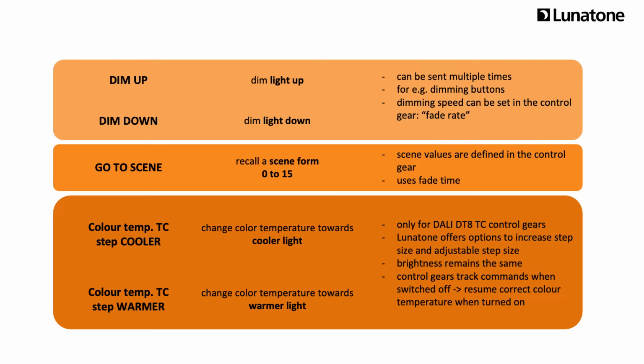Please also note that the commands step warmer and cooler only change the color temperature. The brightness stays the same. Furthermore, control gears react to these commands when they are turned off as well, so when they are switched on, they resume the correct color temperature right away.